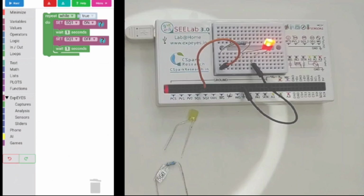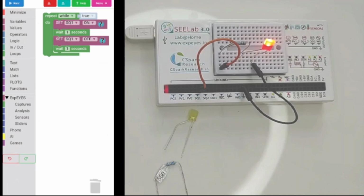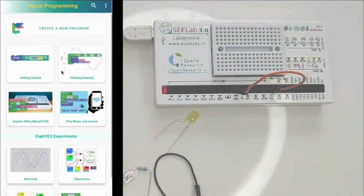Now, let's try something different. I've connected the waveform generator to the A1 voltmeter input using a simple wire. We don't need any ground connections because both instruments already share the same ground internally. If, however, you were using two different instruments, you would have to connect a wire from ground of one to the ground plane of another.